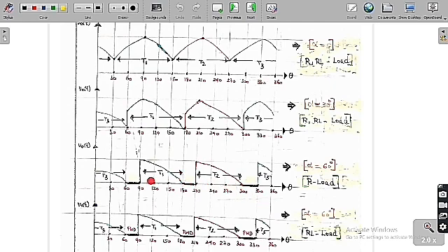So simply we can say that when T1 is on, V0 is equal to Van, when T2 is on, V0 is equal to Vbn, and when T3 is on, V0 is equal to Vcn. So it is going to follow this. But here after 180, in the original case the voltage Van is negative, but here negative cannot be possible. If V0 is negative, then definitely the freewheeling diode is going to conduct. So the freewheeling diode is going to conduct in this region, which is from 180 to 210.